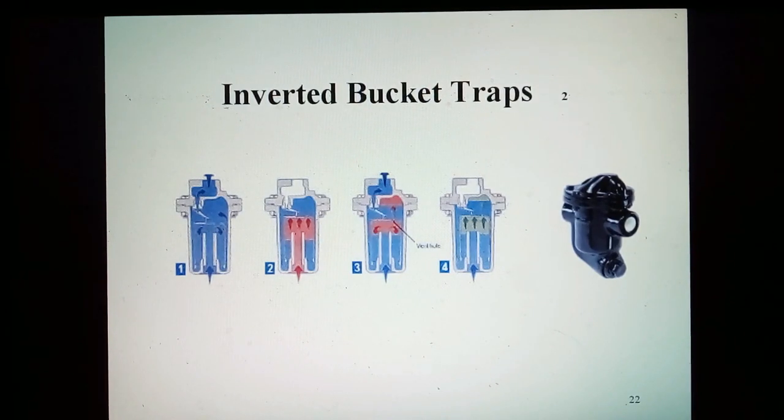Inverted bucket traps. The inverted bucket is the most reliable steam trap operating principle known. The heart of its simple design is a unique leverage system that multiplies the force provided by the bucket to open the valve against pressure. Since the bucket is open at the bottom, it resists damage from water hammers, and wearing points are heavily reinforced for long life.